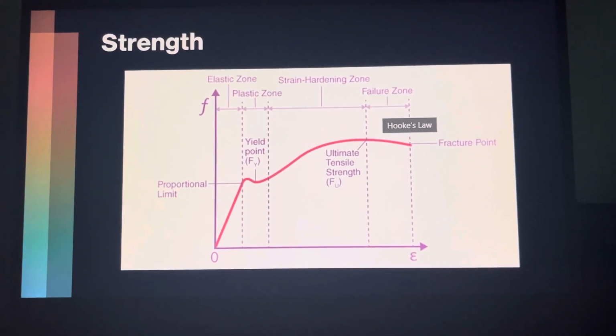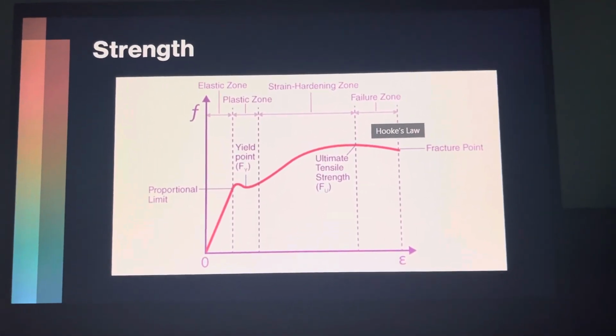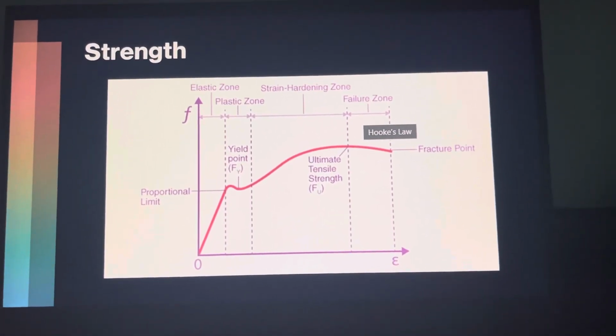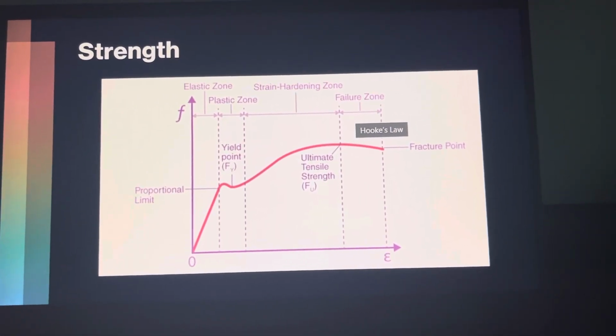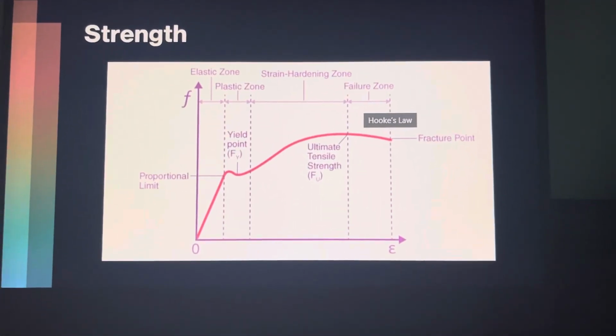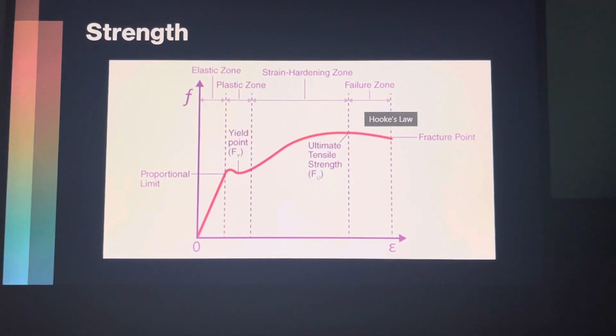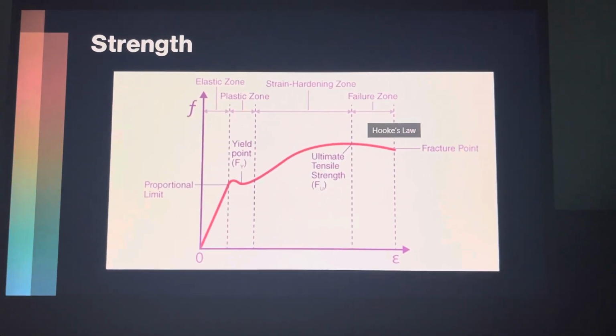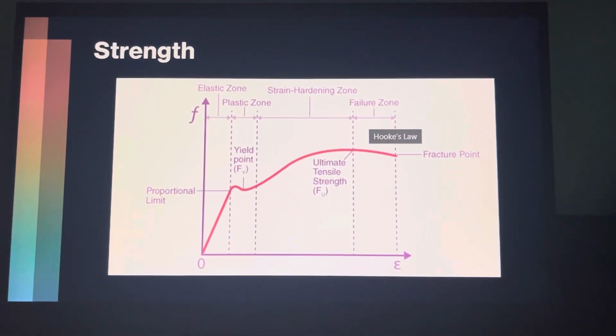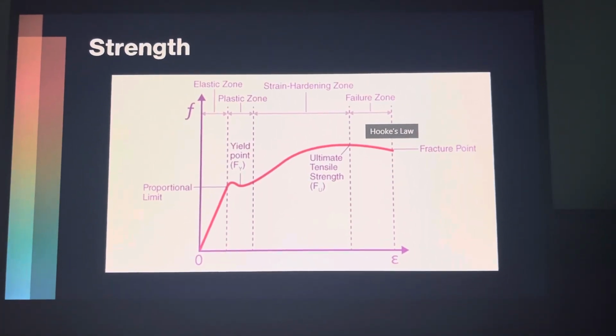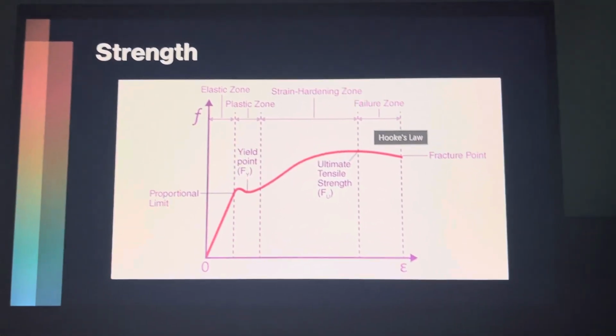A deformation is called elastic deformation if the stress is a linear function of strain. In other words, stress and strain follow Hooke's law. Beyond the linear region, stress and strain show non-linear behavior, and this inelastic behavior is called plastic deformation.